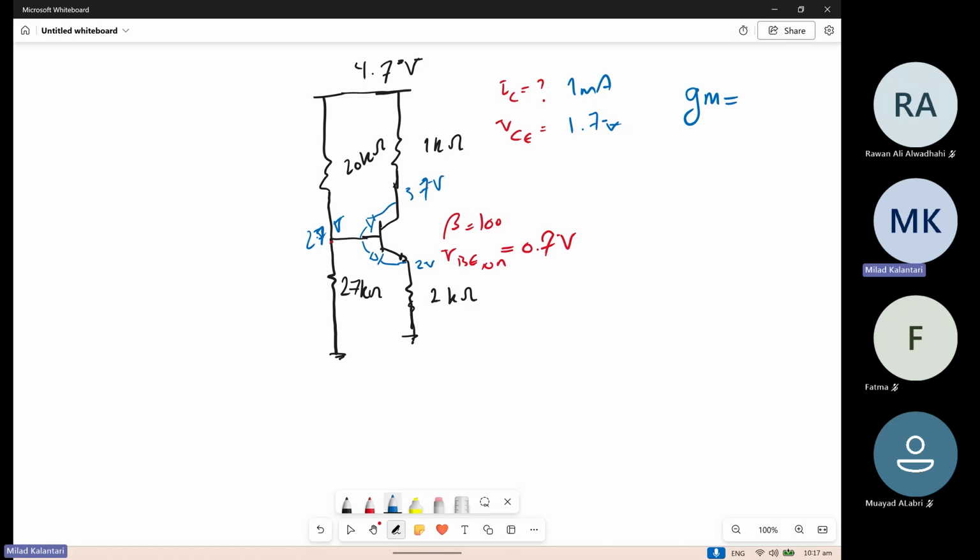So the top diode is reverse and we are in the active region. Saturation in a BJT means that both diodes are turned on. So this is in the active region, so the assumption of the beta of 100 is correct.